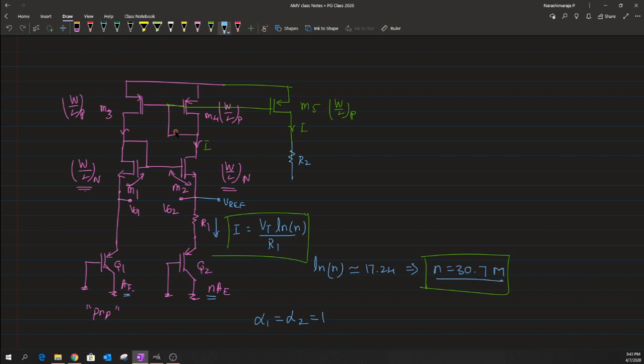As I said, when the current flows through this R2, the R2 basically mimics only the positive temperature, or PTAT, circuit behavior, but we want a CTAT to be added along with it. So what I really mean is that we just need to add an extra structure at the bottom of this transistor as we had for the second branch. The same similar setup has to be added along with it. So now this in turn will give us a value of VB, and this VB is the one that we wanted in order to create this CTAT voltage.